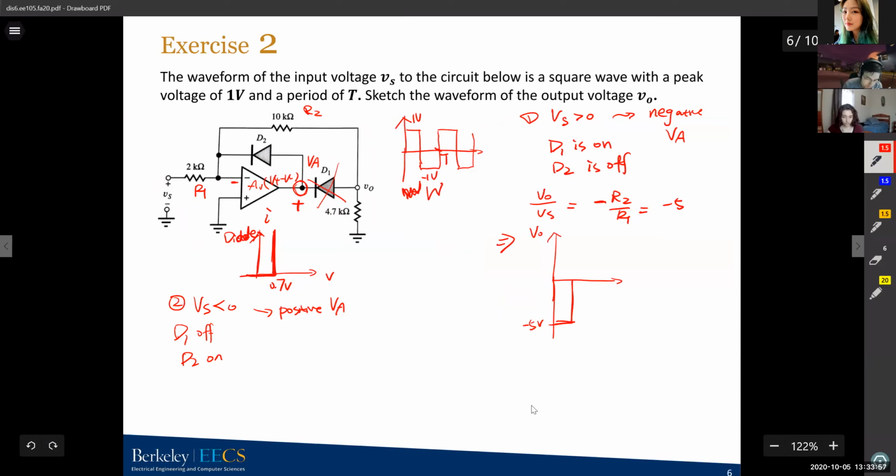So it's different. We have a D2 short circuit here. If we have Vs, we'll have a current flowing through R1, and we have a short circuit at D2 because when the diode is on, the current is infinity. We just have a vertical line directly to infinity. That's the ideal diode. So if we have a current flowing through R1, then all of the current will just flow through the diode.